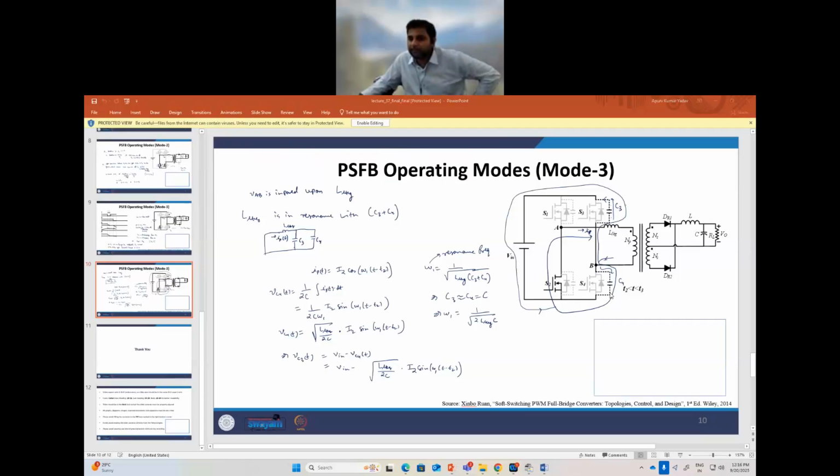But sir, if we consider this circuit which you have drawn here, VC3 and VC4 are in parallel, so VC3 and VC4 should be equal. No, it is not like that. I agree with what you are saying, if it is parallel then voltages are the same, but we cannot say it like this. When the two capacitors are holding their voltages and you suddenly connect them in parallel, one is discharged and one is charged. So what will happen? They will rearrange their charges among them. That is what happens during that instant.